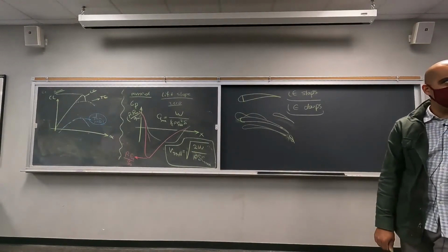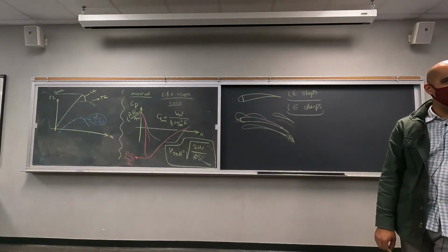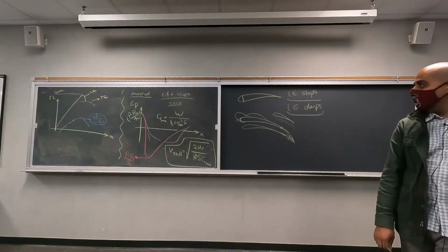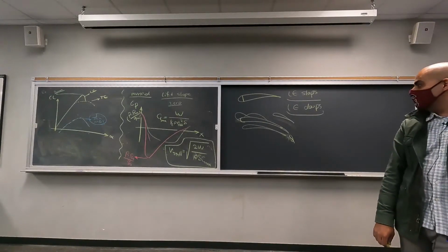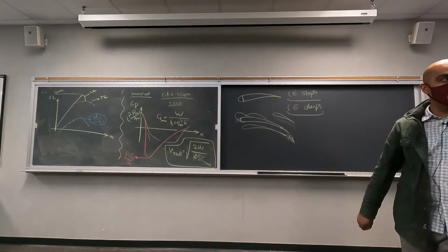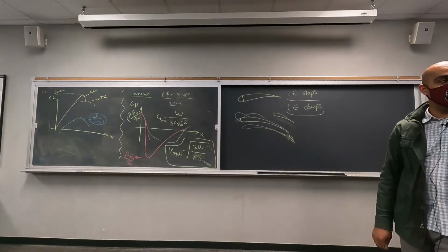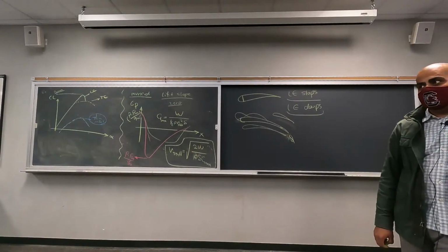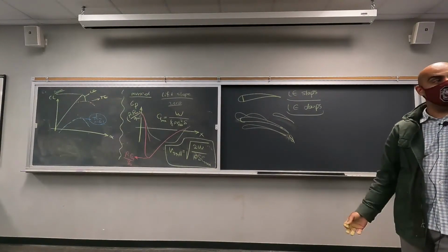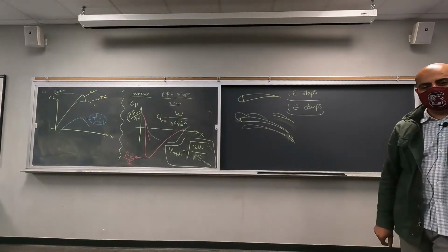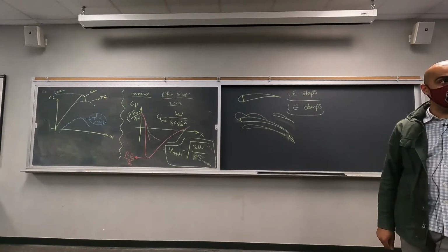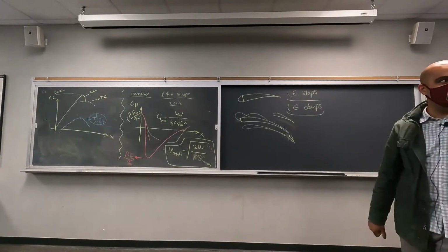What if you ionize the air towards the front of the wing and use magnetic fields to manipulate the flow velocity? Oh, that's a very creative way of looking at it. That's actually something they already do. It's called dielectric barrier discharge, right? You induce plasma on top of the airfoil, which adds a source term to the Navier-Stokes equation. So it is going to push the flow down.